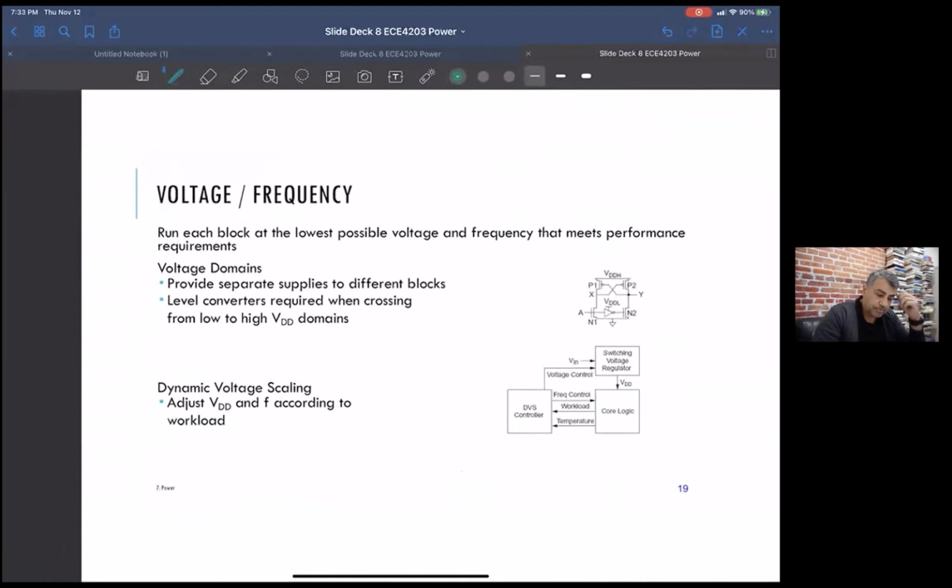Okay, so where were we? It's again CV squared f alpha. The next one to look at is this voltage. The annoying thing about the voltage in this equation is that it's voltage squared. Like I mentioned last time, if you're in an older process with VDD of 1.8 volts, let's say around 2 volts to make V squared easier, that's 4 volts squared. And if you're at a VDD of 1 volt, VDD squared is 1 volt squared.